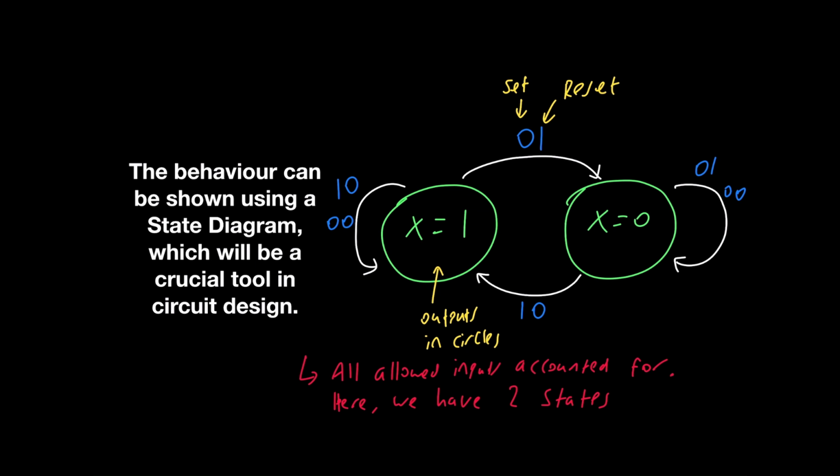This diagram is for a latch, but the difference between this and a flip-flop is that flip-flops change on a clock pulse rising or falling edge, which is used to synchronize changes. You should now be able to see that the simplest form of memory has been made with this circuit. The ability to remember the previous state before it is rewritten is the fundamental idea of volatile memory. Whilst computer memory is more complex and requires more understanding of computer architecture, this is the core knowledge you need.